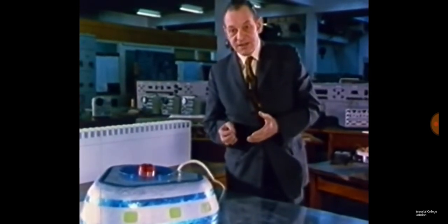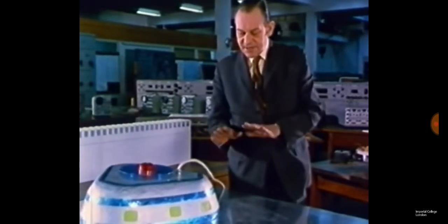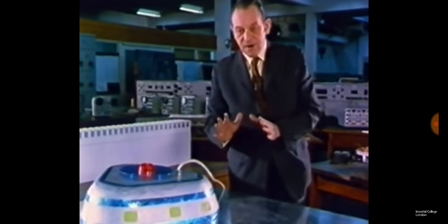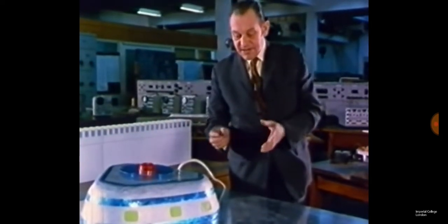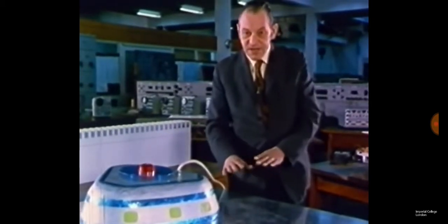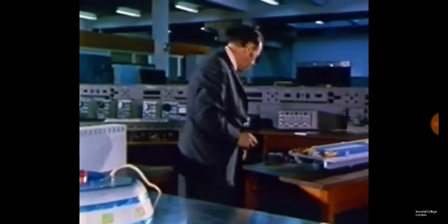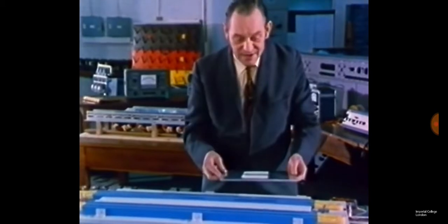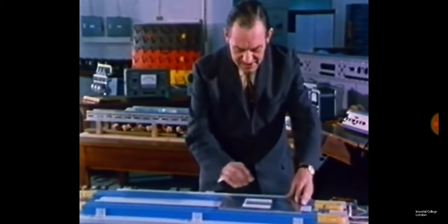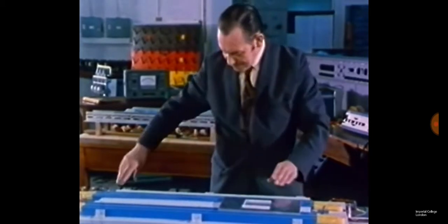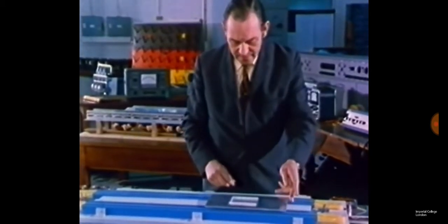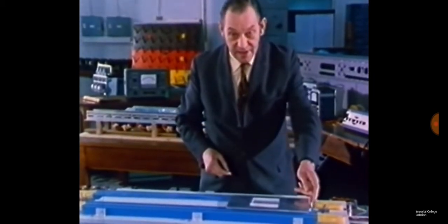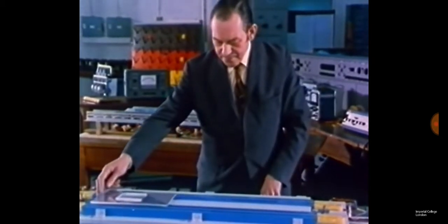But what is concerning us seriously at this time is the possibility of using the same idea, but for guidance along a track, for the possibility of high-speed travel. So let's now look at a levitation system which is only allowed to move in one direction. When this aluminium plate is lifted over this coil system, it will be seen to be free to move in this direction only. The only force resisting the motion is that of air friction, and at this kind of speed there's very little of that.